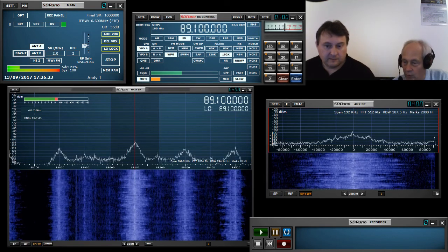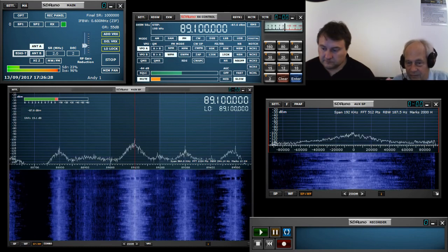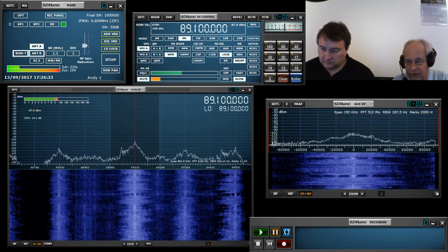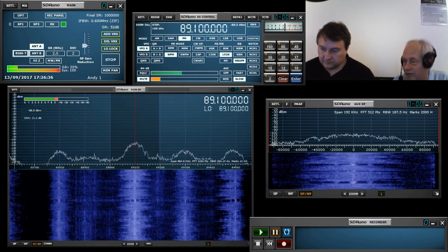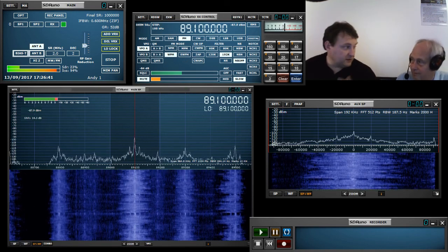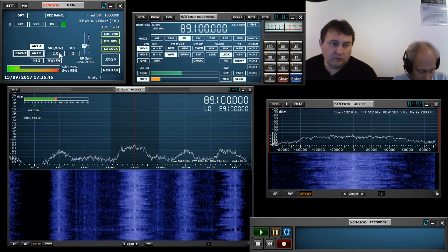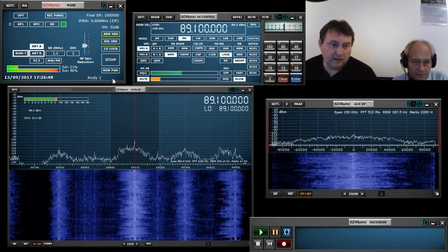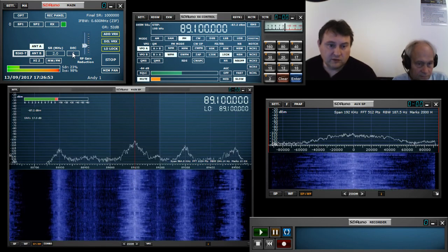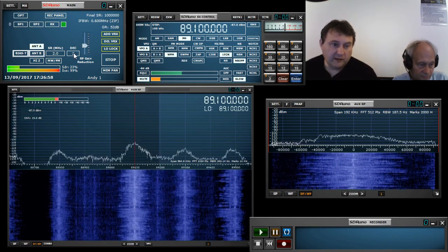And that's probably also worth mentioning. Whatever it is you're listening to, it's worth having the bandwidth and decimation combination down to just the amount you need to comfortably do what you want to. So let's talk about decimation. Natively the hardware supports a sample rate of between 2 and 10 megahertz, and to get to sample rates and bandwidths lower than 2 megahertz, we can apply decimation.